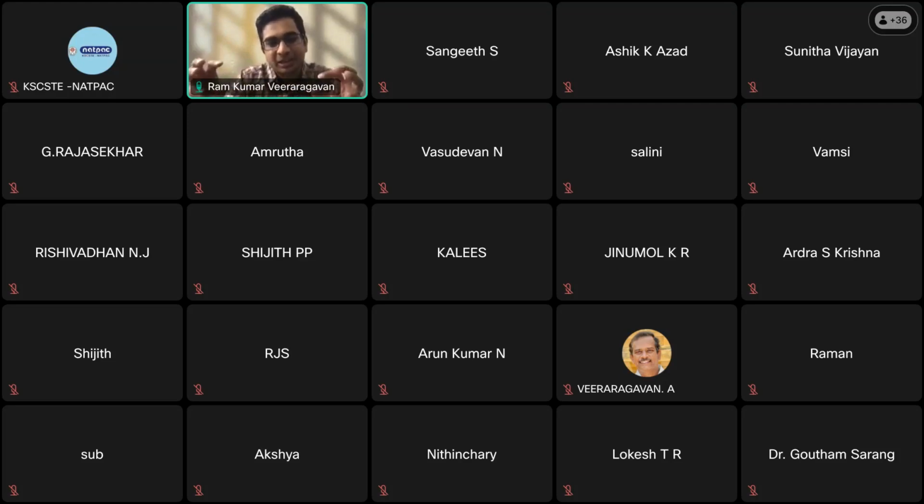So it's based on their overall past experience over the years and evaluating these specific numbers. This number is, to start off, an initial number. These are subject to change over a period of time. In Maine, they started off with 20,000 passes, and now they're backing it down to 18,000 passes based on the different polymers and the RAP that they're using now. They changed it not long ago either. So these changes are based on their needs.